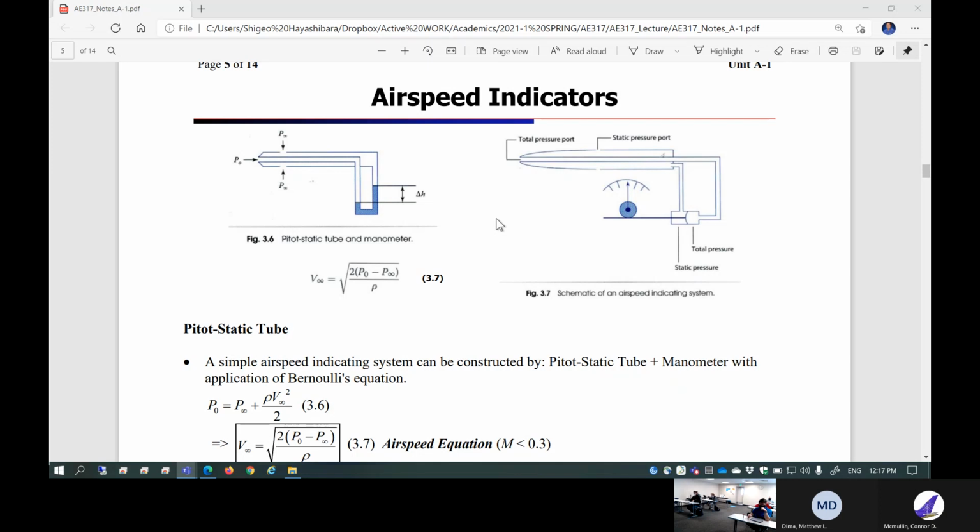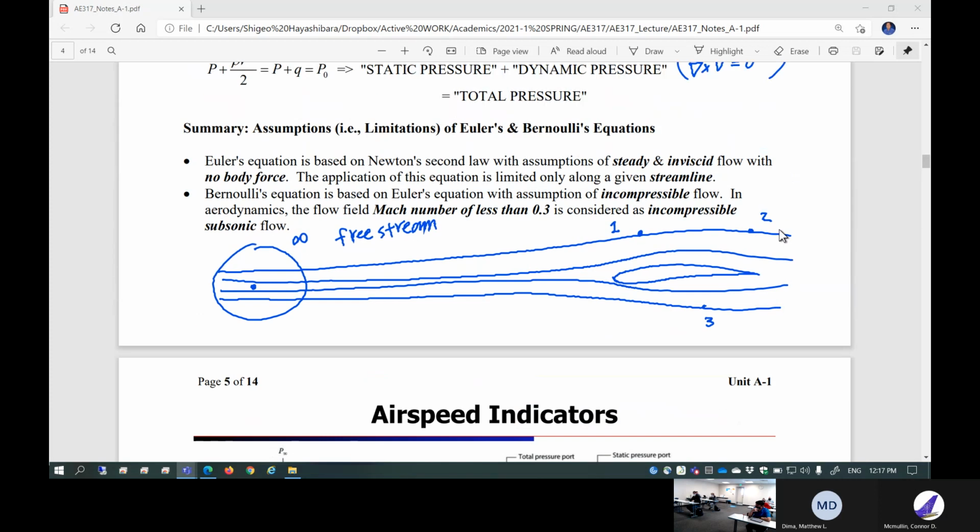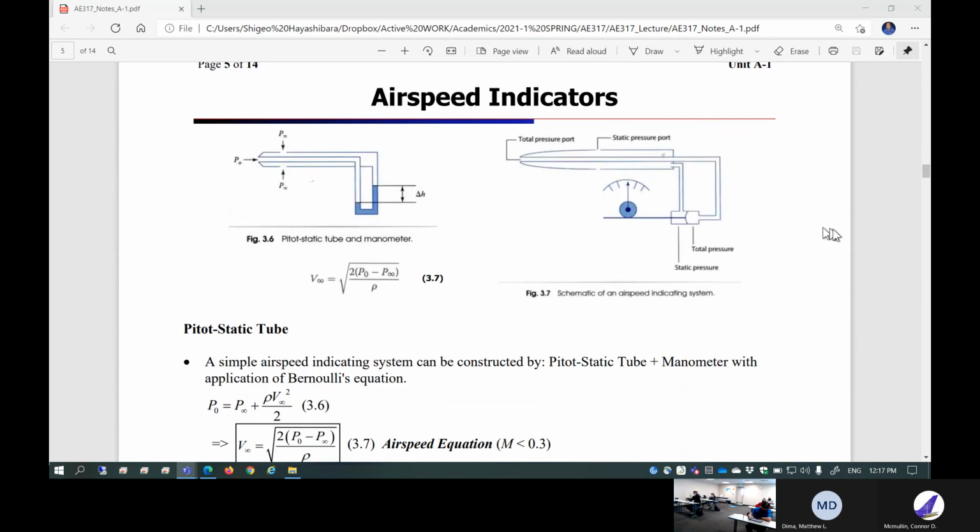After that, you are going to come up with equivalent airspeed. Equivalent airspeed is essentially: if your flight altitude were hypothetically sea level, what would the airspeed indication be? That's equivalent airspeed. And then, of course, you really want to know true airspeed. True airspeed is not always the same as ground airspeed. Those are the things we want to talk about, okay? I think we stopped at page 4. So today, let's take a look at page 5.